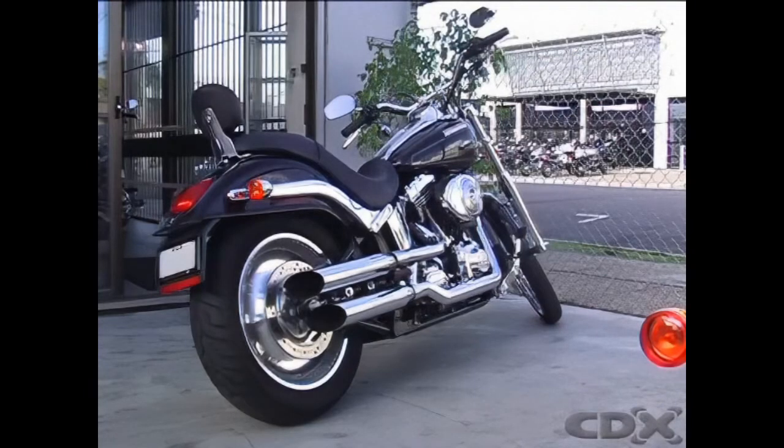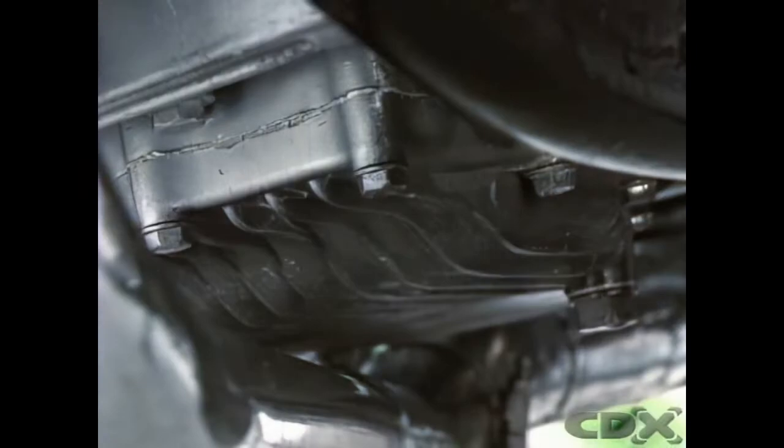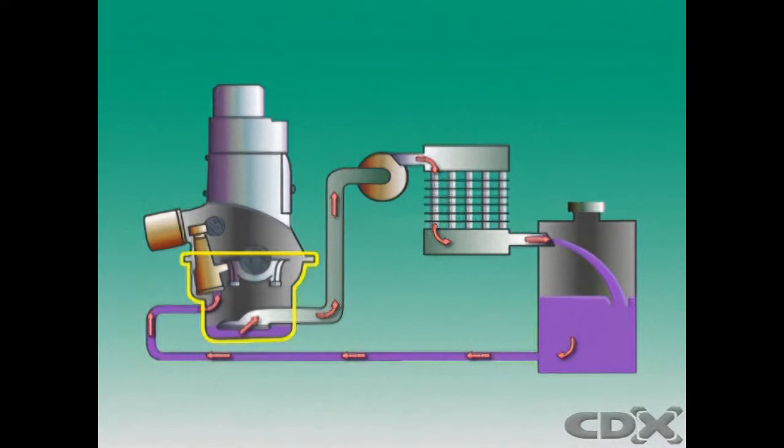The oil collection pan is part of the dry sump system which is used in some motorcycles. It replaces the sump in the wet sump system, but it is much smaller. It collects the oil after it has circulated through the engine and directs it to the pickup strainer on the scavenge pump. Since no oil is stored in the engine in this system, a dipstick that is normally used to check oil levels in the sump is not needed.